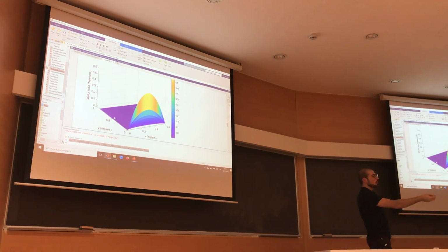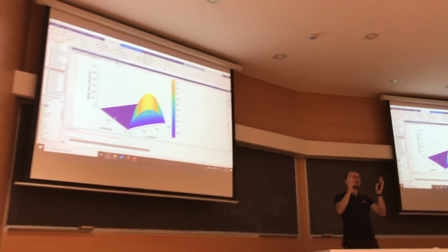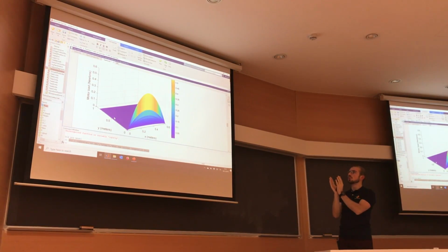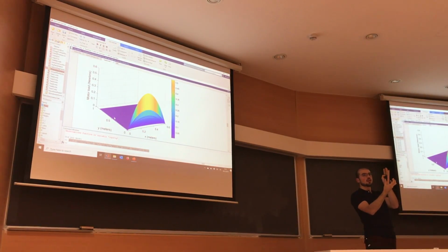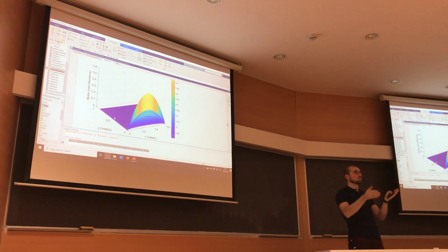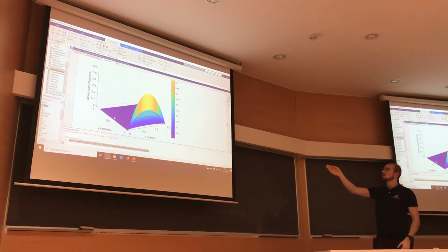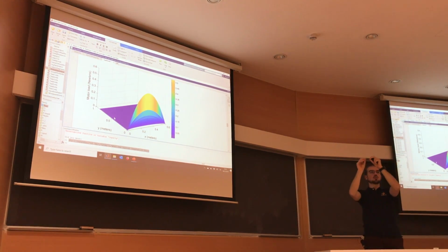On the bottom corner of the whiteboard, you can easily think that you have the two pulleys and the two cables that are really long. So the V that they form with the base is very narrow. So you don't have to put in a lot of force, because all the mass of the rover is well distributed on the two cables. Instead, if it goes up to the top, the V is very large, so it has to generate a lot of power to move to the top corner.